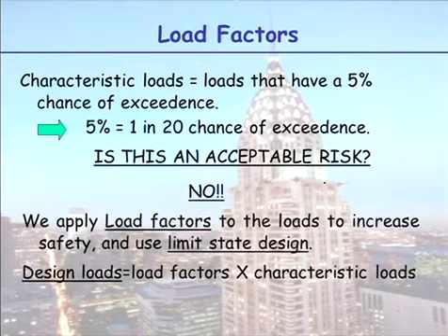So what we do is we get our characteristic load and we then apply load factors to them. We always use the same characteristic loads regardless of what we're designing for, and we apply different load factors. And we call this limit state design. We design right up to the limit. If the yield stress, the maximum amount of stress it can carry is 300, we would do our calculations and ensure we can load it up to as close as 300 as we can. Where our factor of safety lies, it lies in the loading, okay? So we call this limit state design. Our design loads are our load factors times our characteristic loads.